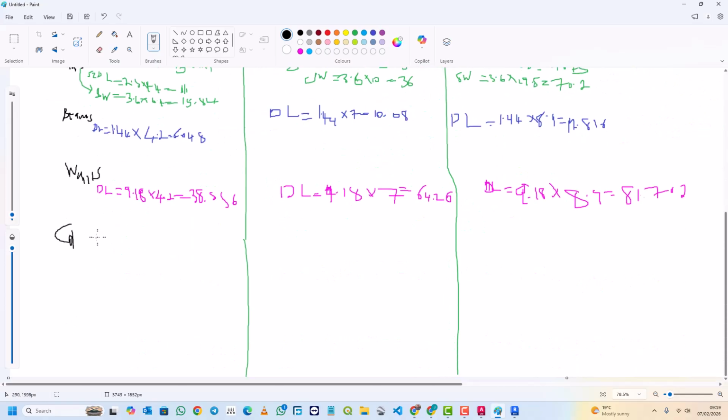If you take a column of 200, this one is also dead load. And for columns, I'll just use, maybe we can use this color, or let me use light green. So this one is also dead load, and it's very simple. So it is 0.2, we will assume a square column of 0.2 by 0.2, then multiply by density. Density is actually 24.